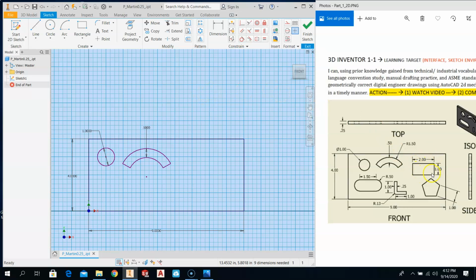Now we want to do the rectangle box. And I'm going to come back and dimension this a little bit more in a second. So rectangle. And this is a 2-point rectangle. Again, you can hover on that. There's different ways of drawing a rectangle. So I'm going to start right here, 2 inch by 1 inch. Looking at my dimension there, look at that, 2 inch by 1 inch. Okay. Now if I want to be real careful, my dimension. And this way they'll show up on my drawing as well. So there's 2 inches. Because sometimes instead of 1 inch, it might be 1.9995 and it looks like 1. This way we're sure it's exactly 1 inch.